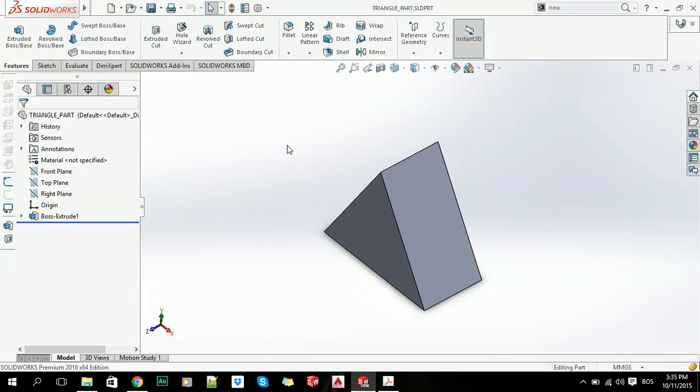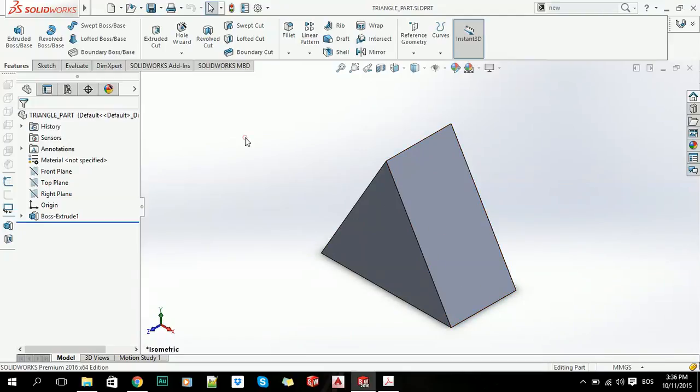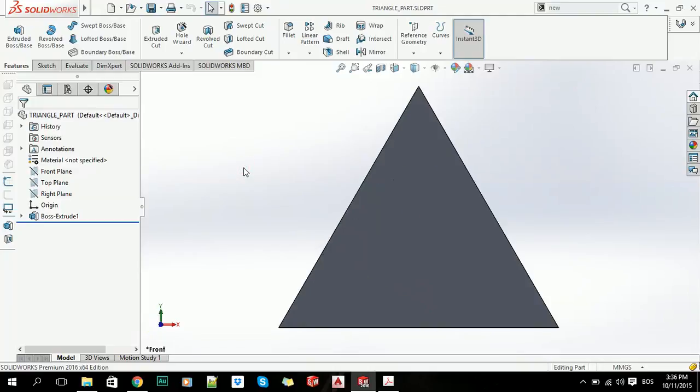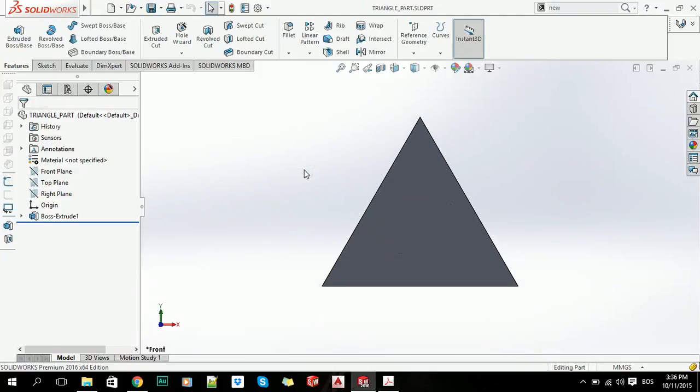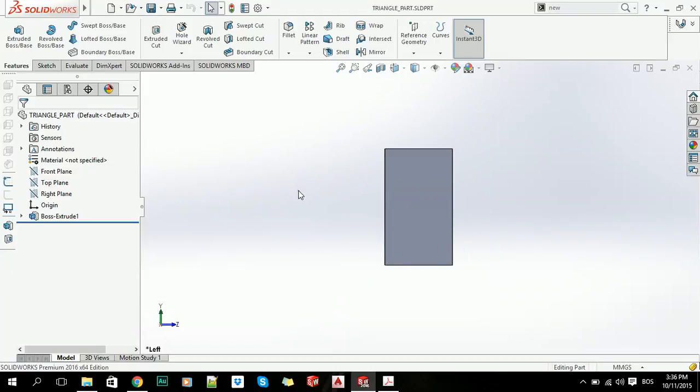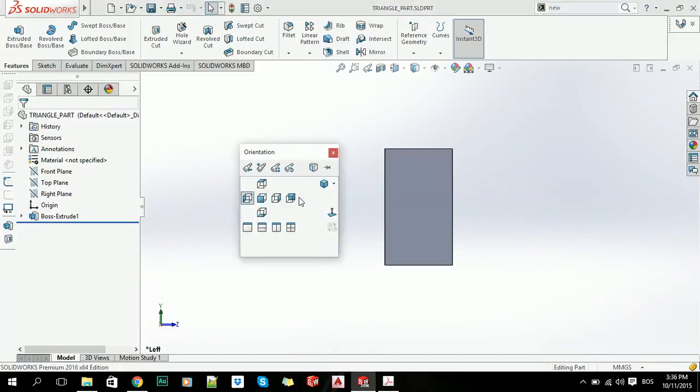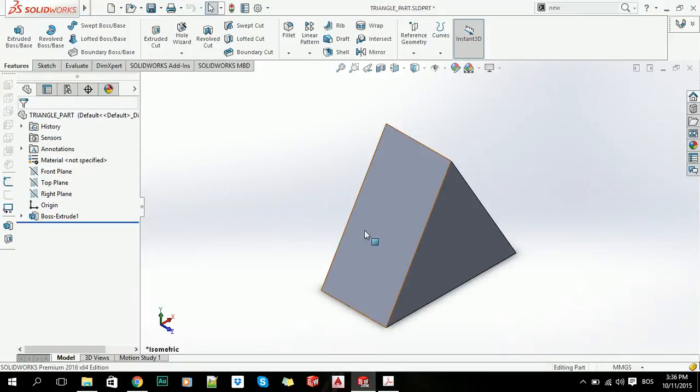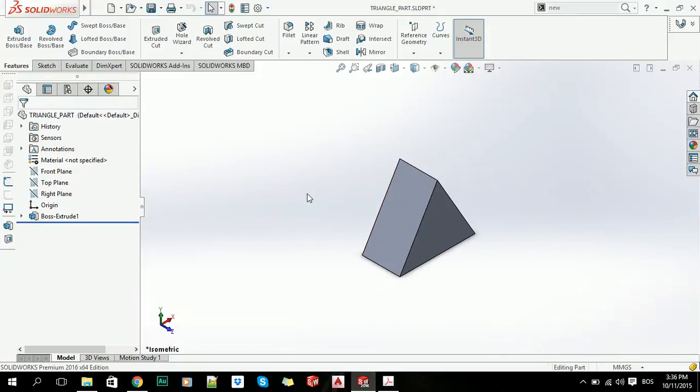Also, this is just extra: if you have this isometric view and now this is front view. So if we want to specify, for example, this to be our front view, we go to this, which is Control+3, then we press space and we can create new view and we can update standard views. So we click on update and then click on front view. We want to make the change, and now when we go to isometric, it's different. So basically that's it.